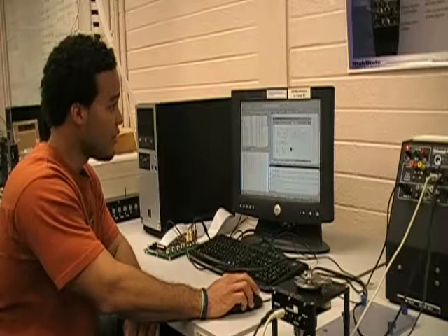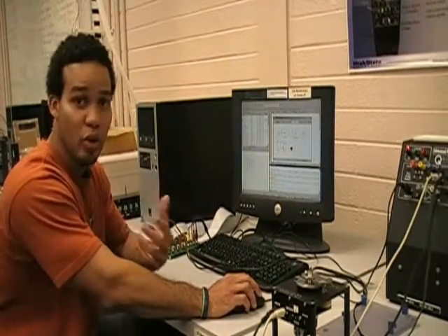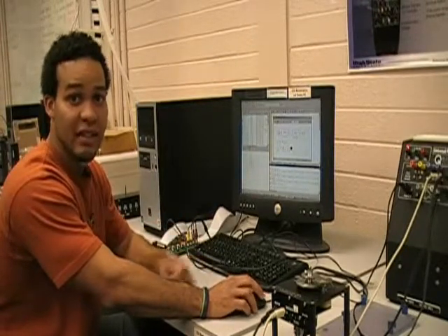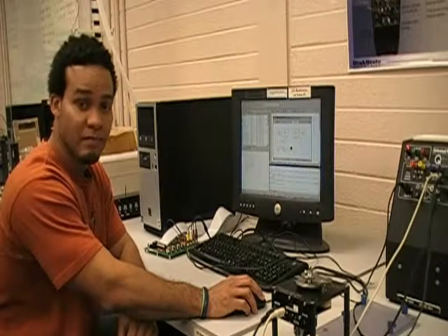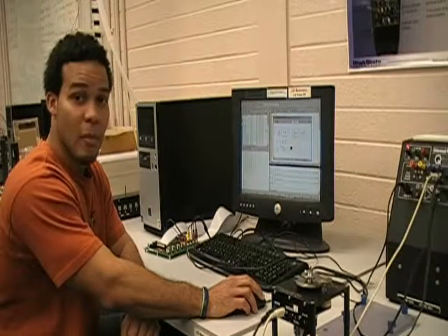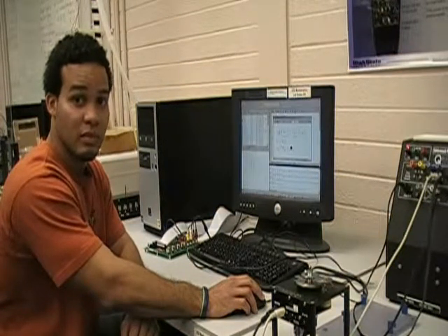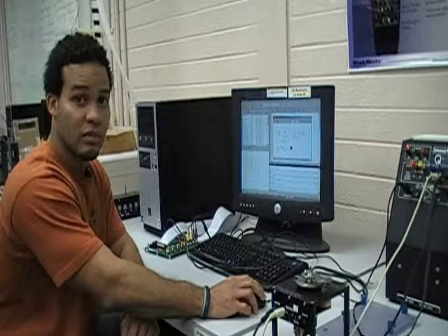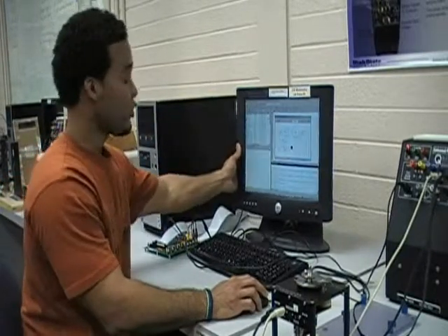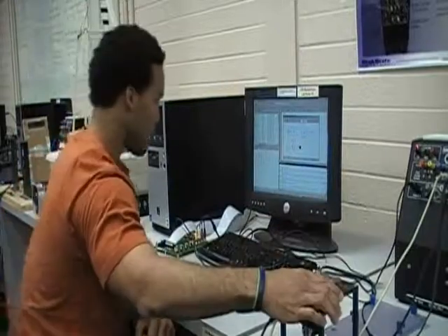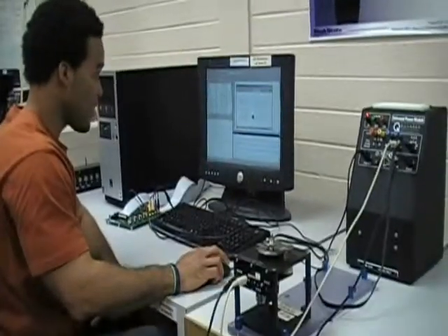Remember, if you are using constants from your code, you first have to run the code and then build the simulation. If you have constants in your code that you use in your Simulink model, the constants initially are not in the workspace where they are picked up from for compilation purposes. So you can enter any dummy variables in the MATLAB command window or run those lines of code so that they are in the workspace. Right now I'm going to show you the simulation, how to get the data from the motor.